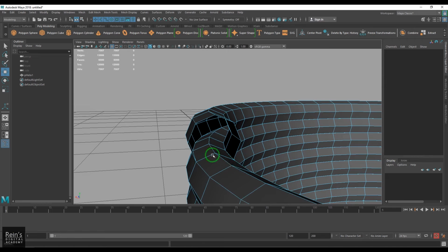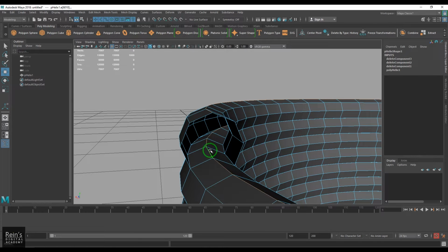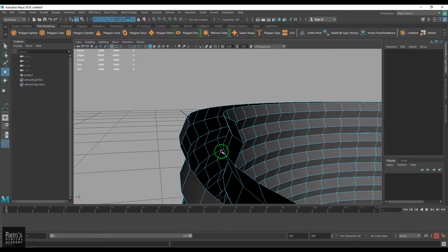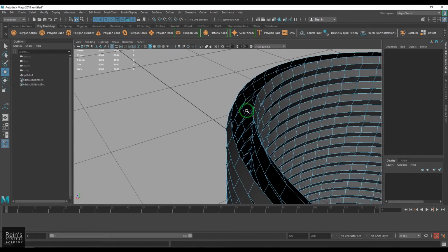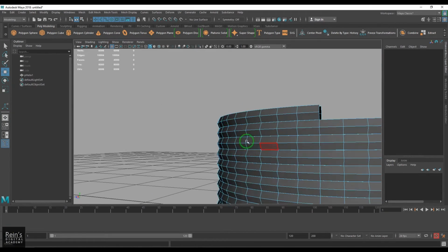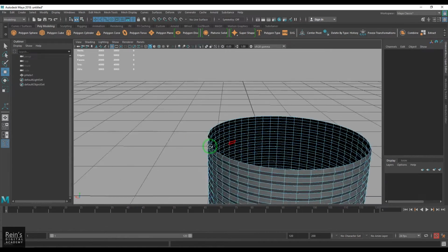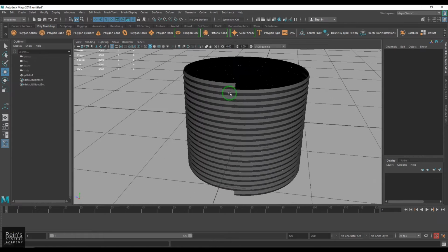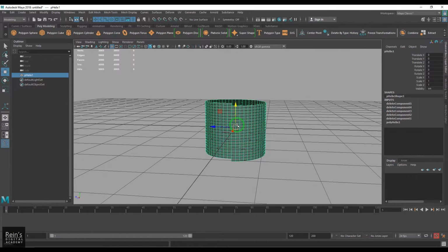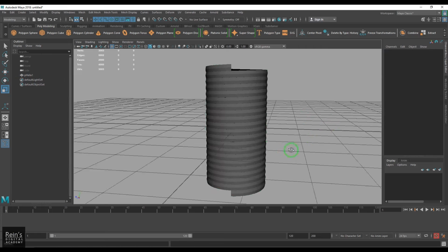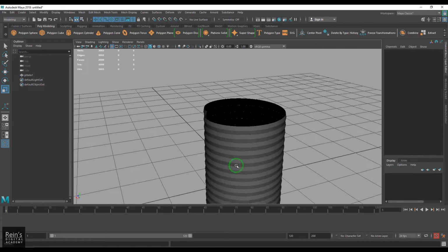Very similarly, I just wanted to delete this line also, convert selection to faces, hold control right click, then to faces, and then delete them. Now you have deleted the faces which are inside. Now I just wanted to use the outer part, double click inside one and delete it, and that's the easiest way to build this up. You can increase the height if you wanted it to be, and then start exploring this.